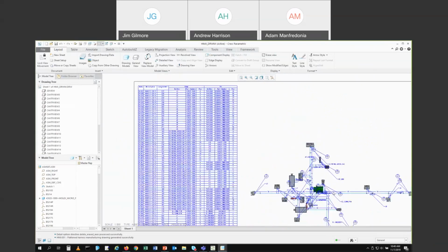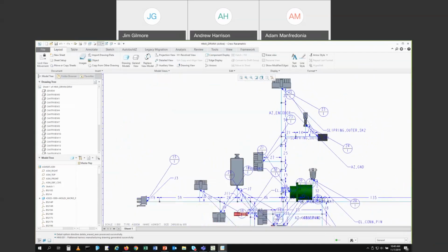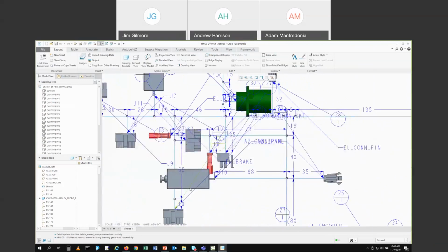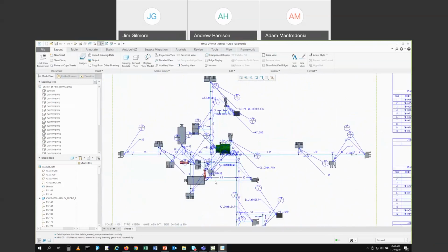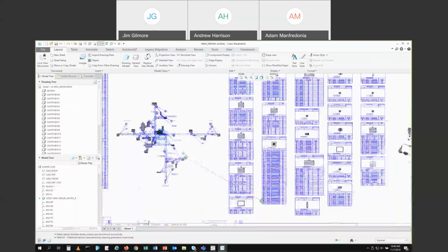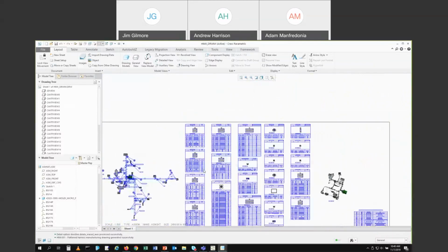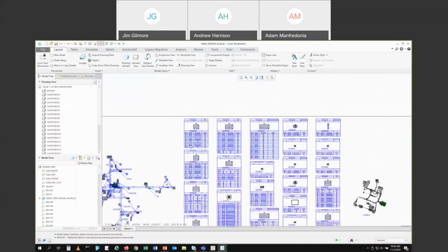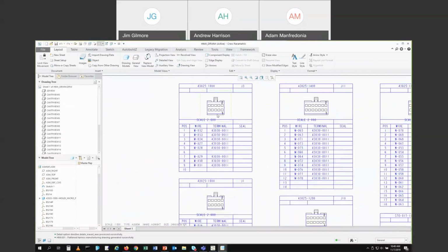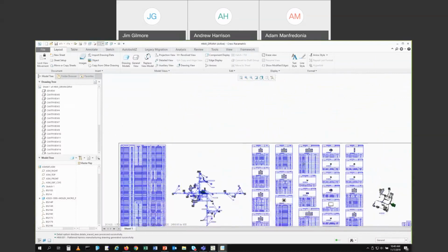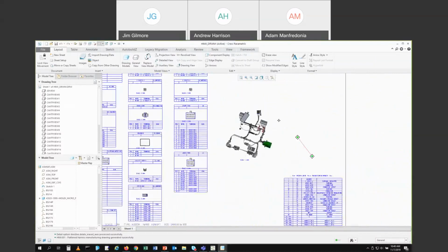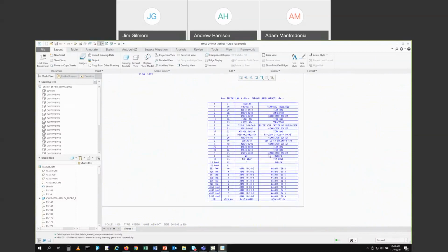Again, you might want to reposition and move some of these as far as the angle so that you eliminate some of the interference conditions. So for example, this one here, I'd want to rotate down. This one I'm going to rotate over. So there's some cleanup work that you're probably going to have to do on these things. Again, look at the number of tables that it developed for each one of those components. We're seeing a view of the connector, all the pins, the wires and which pins they're associated to, our 3D view of this, and then all the way down to our bill of material.